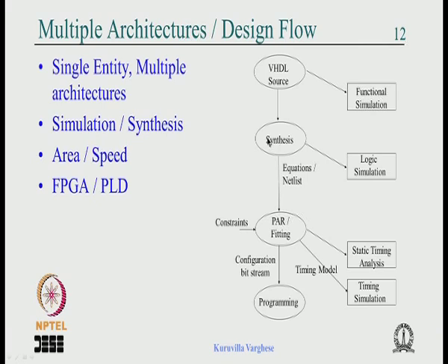Then you go for synthesis, where you generate from the written code the netlist or the equations, that is, the logic circuit in terms of gates and flip flops. Sometimes this synthesis tool can be quite smart and linked to the next processes. Sometimes it will generate a circuit which is very specific to the device you use. Maybe the FPGA has some kind of combinational circuit elements, and the synthesis tool can generate the circuit in terms of those.